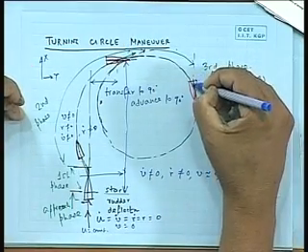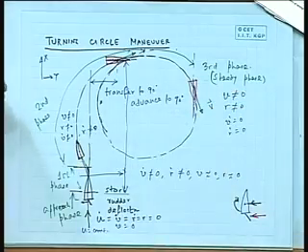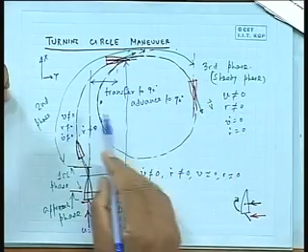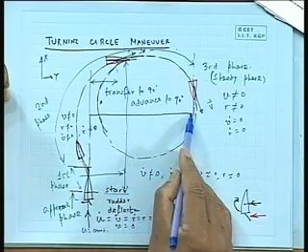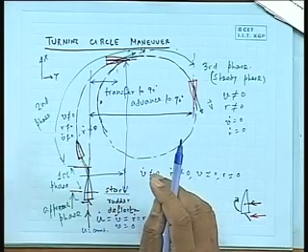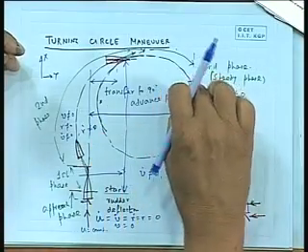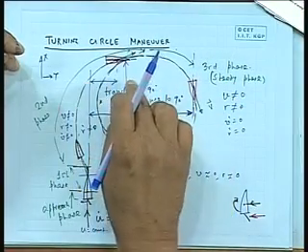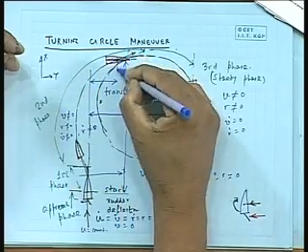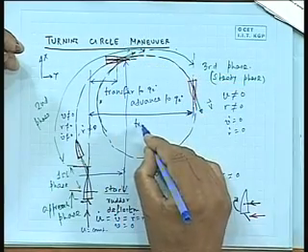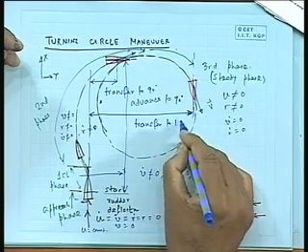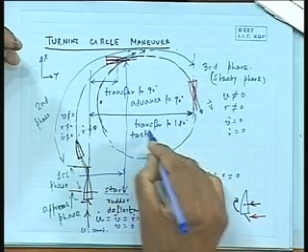Same thing would of course occur at 180 degrees. This is where it has changed to 180 degrees, just opposite. Then obviously from here to here is the transfer at 180 degrees, and some people call it the tactical diameter. This is the distance where the heading has changed 180 degrees, and that transfer at 180 degrees is called the tactical diameter for a ship.